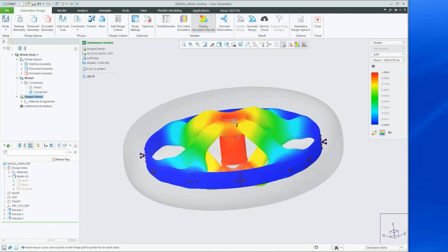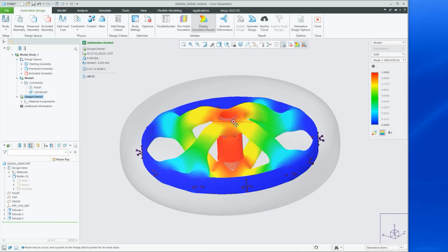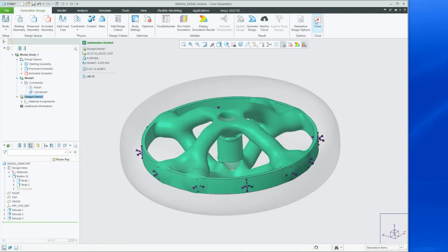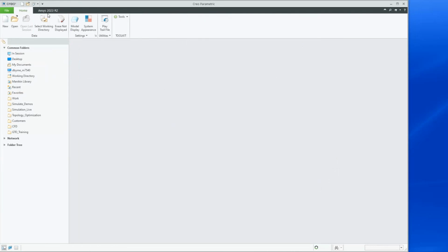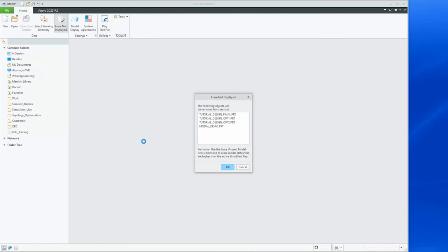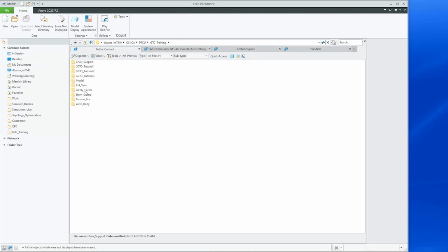available space is this. Now you can actually combine a static study with a modal study. So you can create an optimized design that is optimized both for static loading and also for dynamic loading. All right, great. So let's close that one and let me see what else we've got. I'm just clearing out my memory from the background.